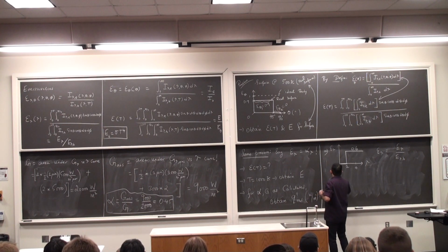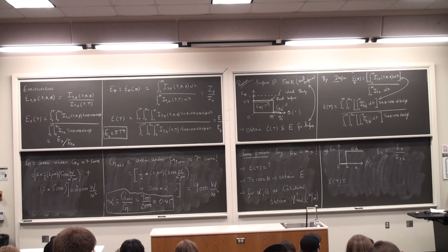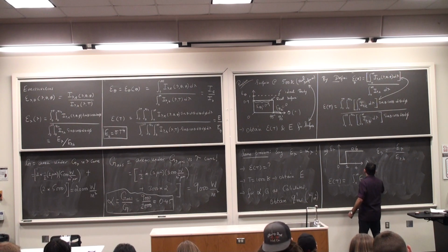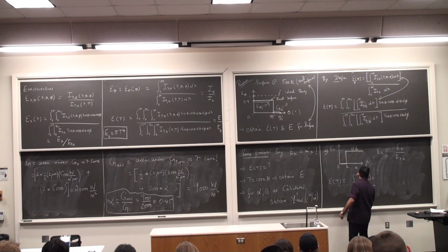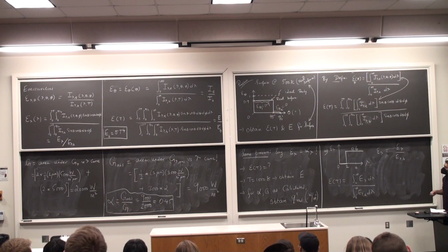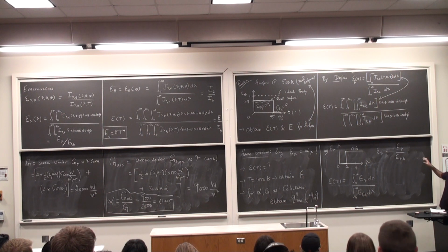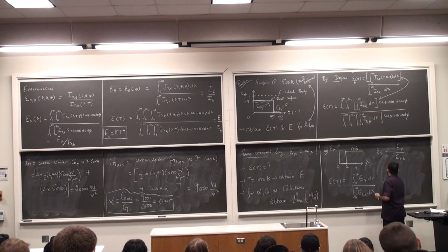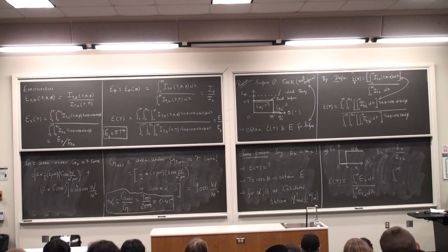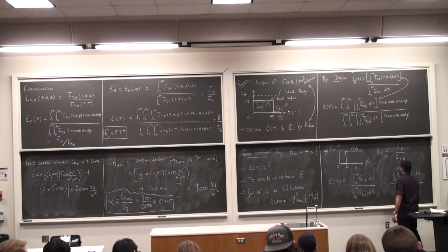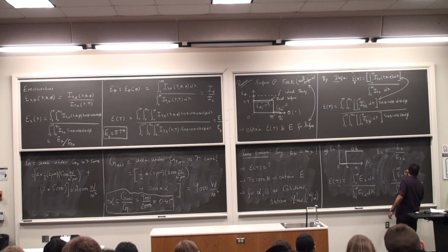So epsilon, which is the total emissivity, different from the absorptivity, okay? Epsilon of T is integral 0 to infinity E lambda d lambda, over integral 0 to infinity E lambda comma b d lambda. Does this make sense to everybody? This is the basic definition. I did not write the integrals. We had them written in the first panel right out there. Epsilon T is nothing but taking all of those over the entire range of wavelengths and then integrating the spectral emissive power. Substitute. So this is integral from 0 to infinity. Instead of E lambda, I'm going to substitute epsilon lambda times E lambda comma b, d lambda, divided by integral 0 to infinity E lambda comma b d lambda.